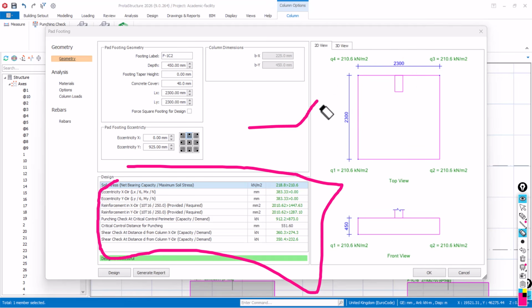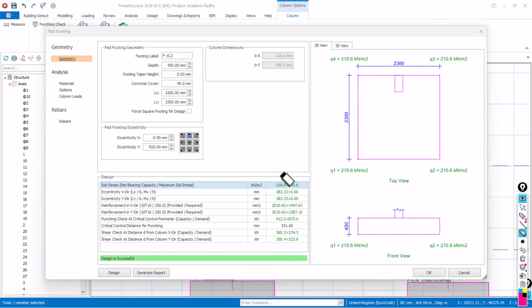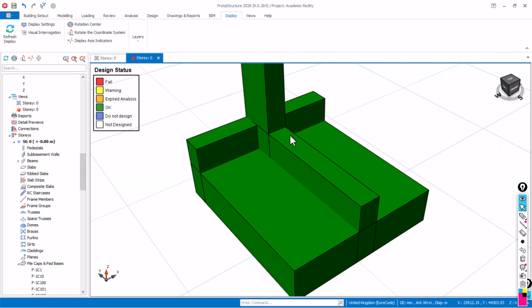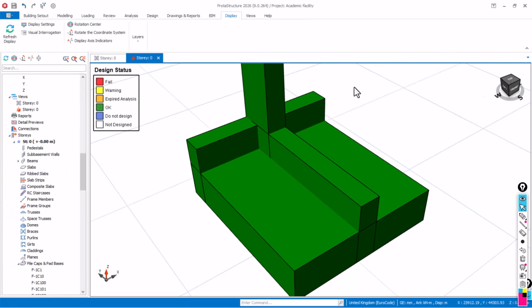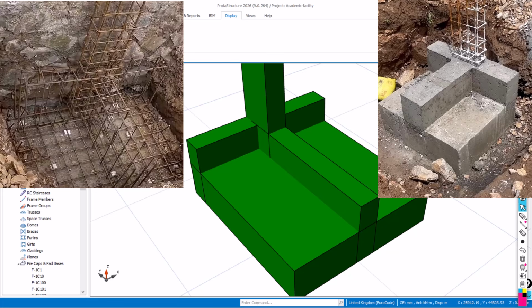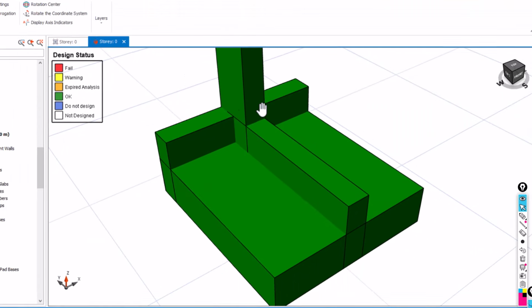And the most common mistake people make is to design eccentric footing in a very different way. For example, as you can see on this particular one, this is what someone designed during construction, as you can see also in the site picture here. Now, this software says it is okay, but based on structural engineering standards, this will fail based on uplift.